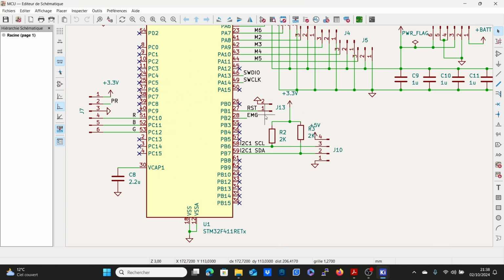One last thing that I want to mention is if you're sure about your configurations and your code, that you define everything correctly, but your device is still not working, you may have a logic high level problem and you need to use pull-up resistors on SCL and SDA. Here I'm not using my Nucleo board, that's my custom STM32 board, and I have these pull-up resistors on my I2C pins. But I'm also using the internal pull-up resistors of the microcontroller as well.